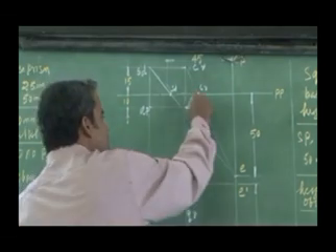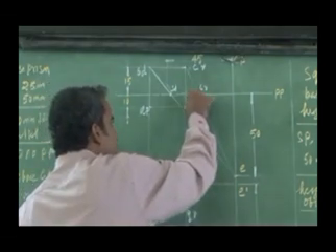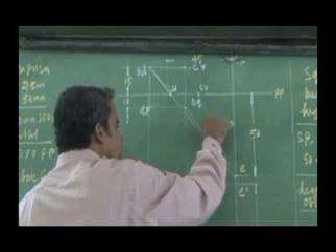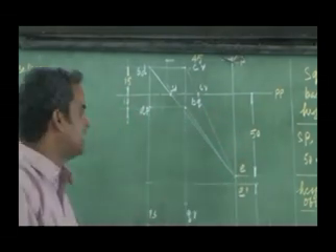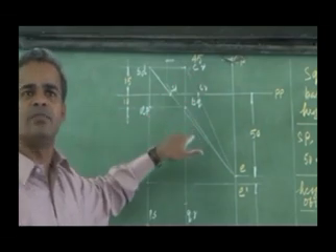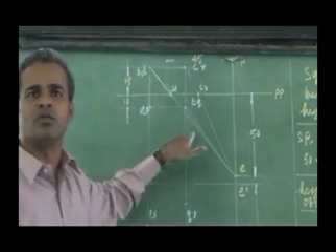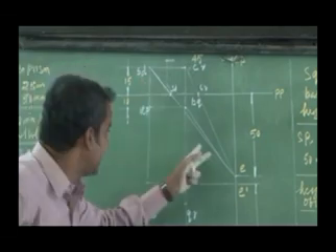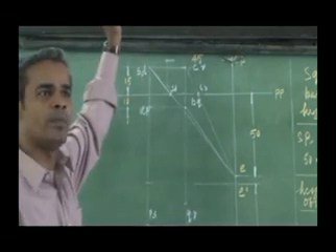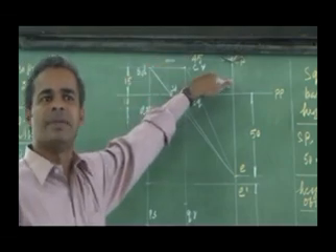Suppose I join BQ. Listen, this is important. Suppose I join this BQ to the visual ray line, does it intersect the picture plane? It is not intersecting. To get the intercept, what do I have to do? I can extend it in the same manner to make it intersect the picture plane.